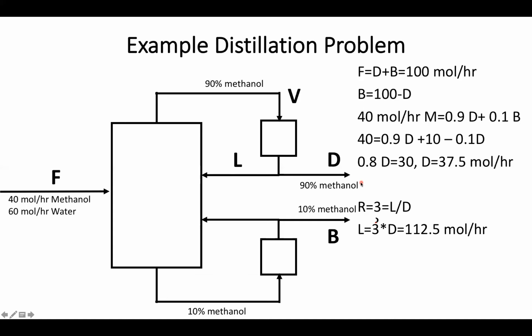So this is one of those things worth noting, that often we have to be pumping in a fair bit of liquid to help keep the column itself running smoothly. So this means that I'm pumping in over 110 moles per hour of my distillate product right back into the system to help keep it functioning smoothly.